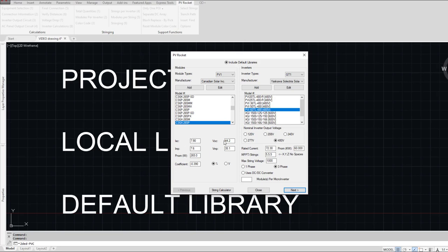So there they are, 7.9 and 44.2. Now, which library, you have to ask yourself, did that information just go into? The answer is the project library. So if we did something to access the local library, it would go back to the defaults. The way we access the local library is I'm going to click here on the model number and re-import the local library, and I did that, and it went back to 8.1 and 43.9.